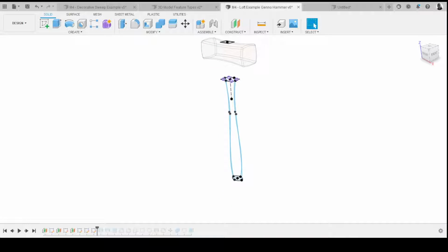So obviously, as I say, we could do that by doing a number of profiles, but actually that's going to get really hard to do because at some point that rectangle is changing to an oval. And how are we going to do that in our own minds? How do we draw that kind of shape and know that it's going to be right? So we don't want to even try doing something like that. We're going to use guide rails instead to make it easier on ourselves.